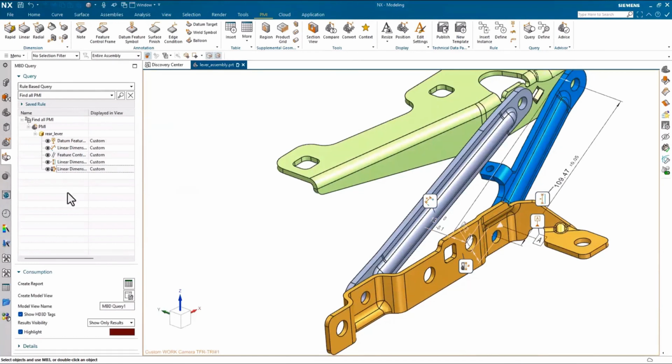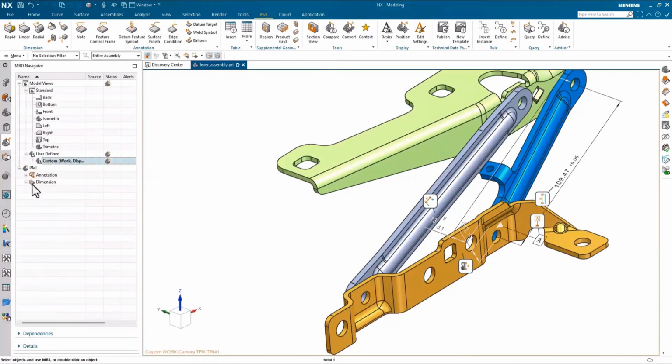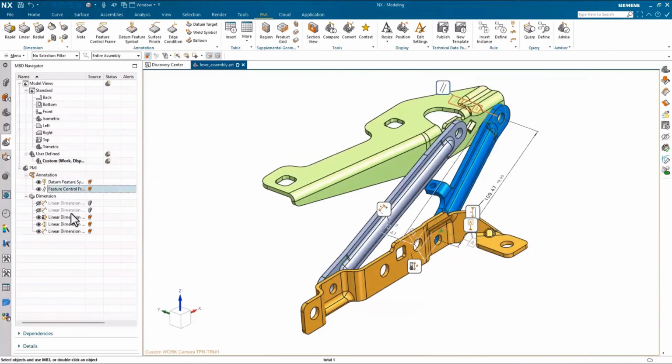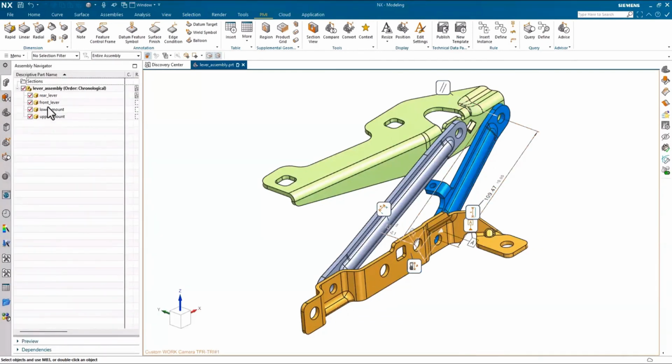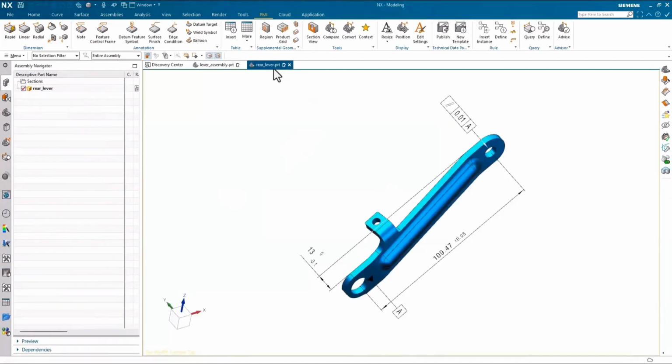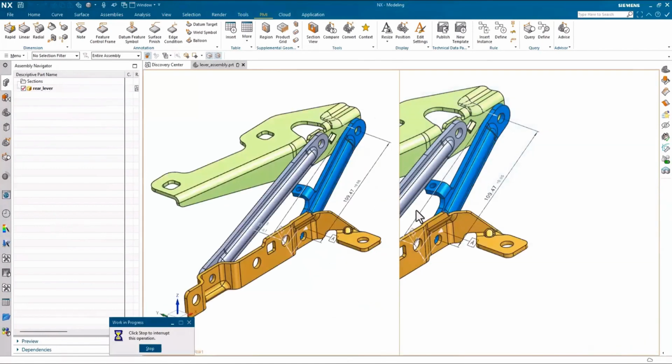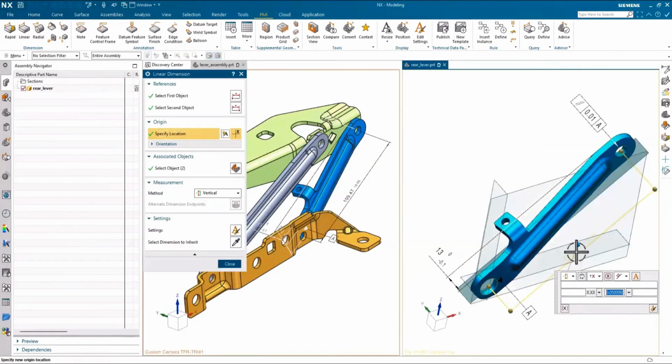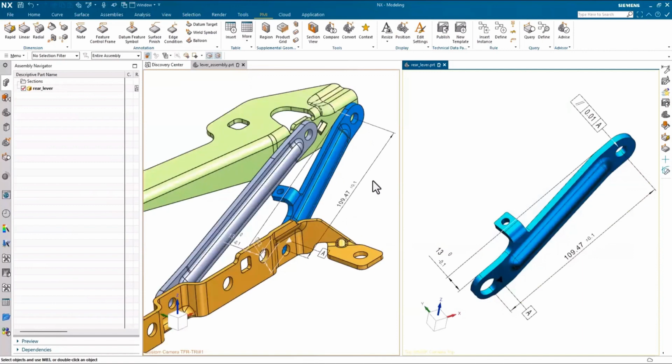finding it within the parts. Again, as you get more detailed and more complicated, you want to be able to bring that to the forefront. And so the idea is, this is just a view of that information. If I want to make changes, I'm going to still go to my master part. So the front lever will go into that and make any changes that we want to. So if a designer's working on one piece, I'm working on another end, maybe Brandon's working on a third, this allows you to do your work. It's still going to pass through to the top level.